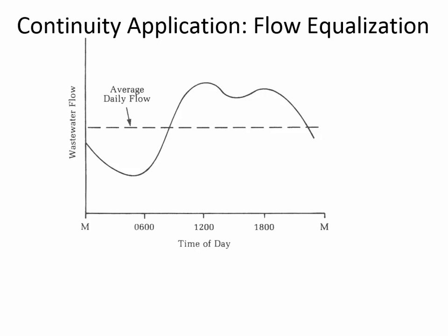So we'll do an Excel spreadsheet in environmental engineering where we look at how big a flow equalization basin should be so that we steady the inflow and the outflow. And more immediately, in the project that you'll be taking in hydraulic engineering next semester, we'll do the reverse of that, which is a water storage tank, where you have a varying outflow but a steady inflow. So it's the same idea of breaking this up into hourly pieces and looking at flow in versus flow out, and that tells you the required size of the tank.